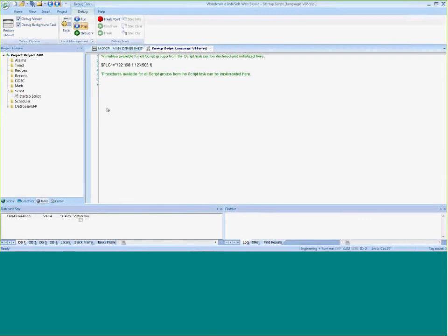And then I'm going to paste that cut that I did earlier, wrap that with my double quotes. So now if I had 13 different PLCs, I could do that all here in this one location as opposed to the maybe 7,000 different addresses that I had in my driver sheets. So it made it a nice, clear, convenient, easy mechanism to do this, and you wouldn't put the curly brackets in there. So just to make sure everybody understands this, this is $sign PLC1 equals, and then in quotes, the formatted IP address that would be matching the particular driver that you would need.